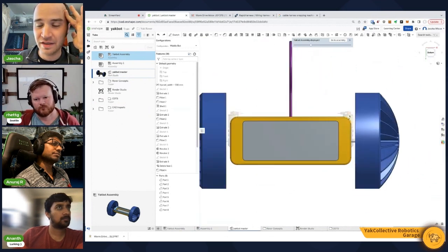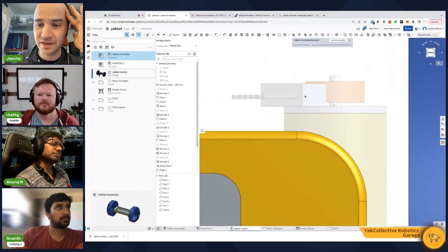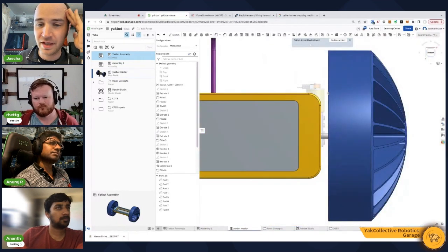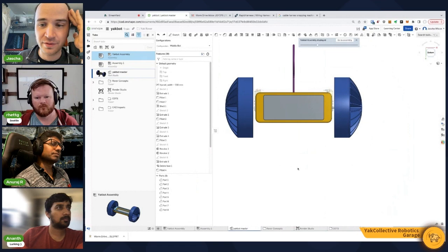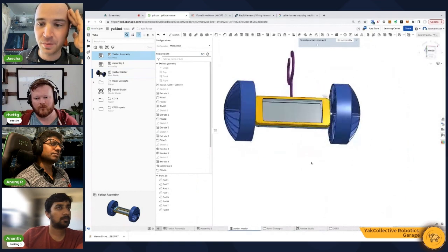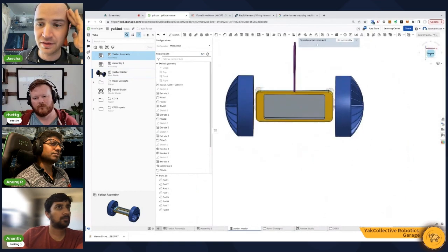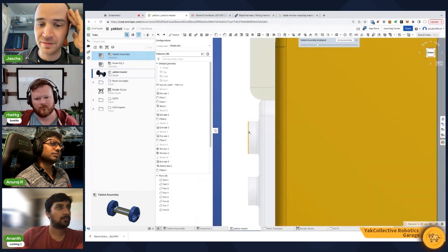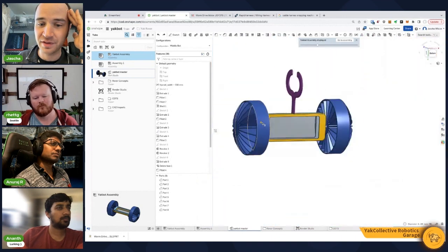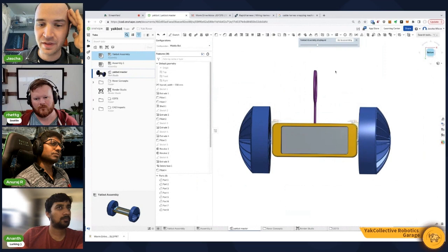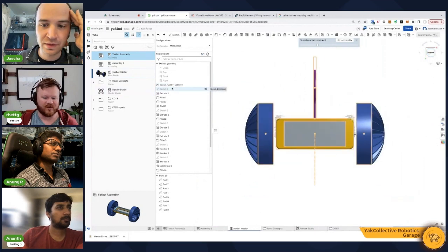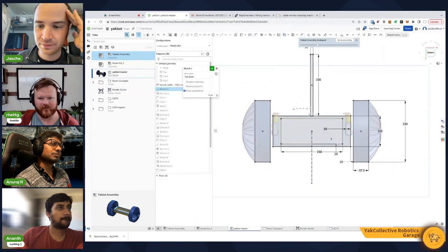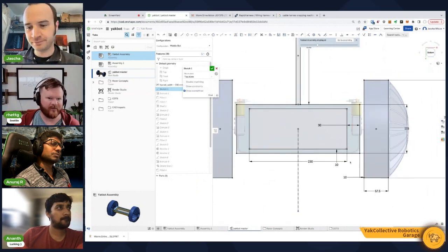We're in context editing right now, so we can see the parts, but then we're going to edit the model in real time to flow around those parts, and we have the full power of section view and everything to evaluate the geometry. We can also see how it's letting me select this line. We can actually reference this geometry out of the assembly itself into the part, which is very powerful. I have several times in Fusion 360 confused myself because it's just the visibility of certain components being there or not.